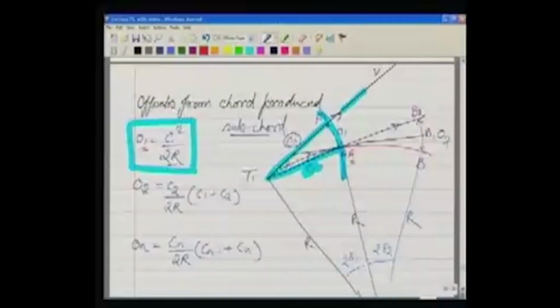So what we do, this chord is extended further. So it is being extended like this. Extended means there in the ground, I have a ranging rod at T1, I am standing at the point A, and this particular direction I am taking it back. We can extend it by any method. It's a problem of ranging.